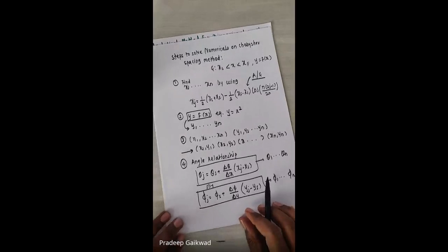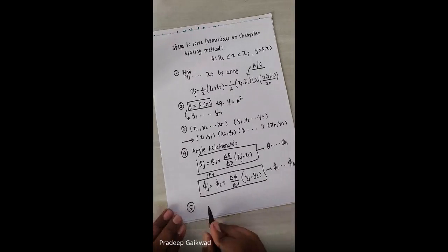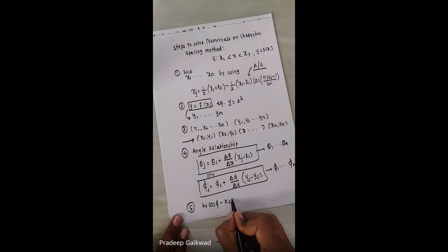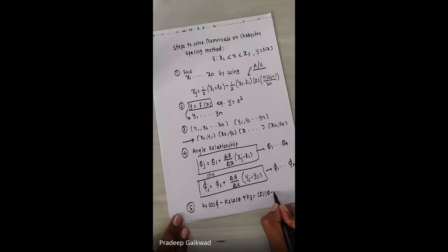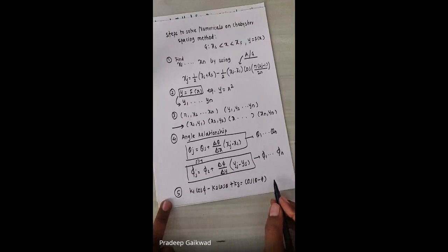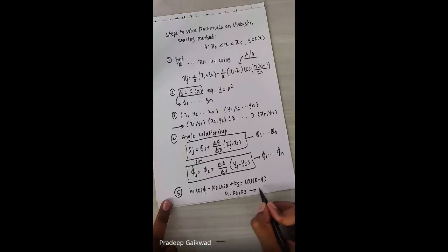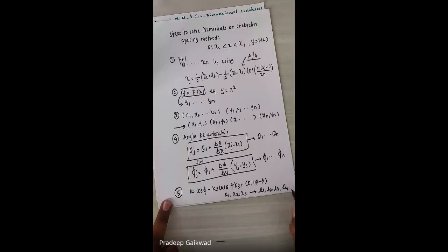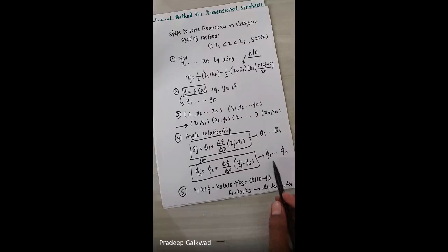In addition to this, if they ask you to find the dimensions, then use Freudenstein's equation, that is k1 cos phi minus k2 cos theta plus k3 is equal to cos of (theta minus phi), for 3 positions, and get the values of k1, k2, k3 to obtain the values of L1, L2, L3 and L4. The last step I just discussed in brief, as we discussed at the end of the derivation also.